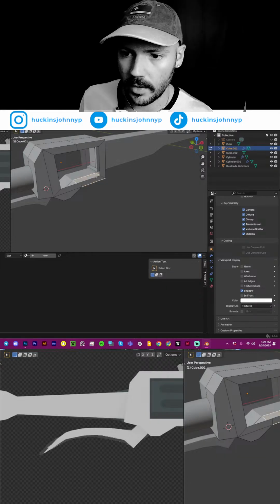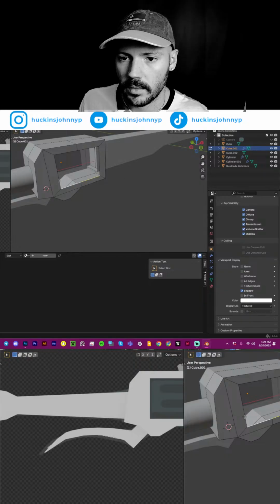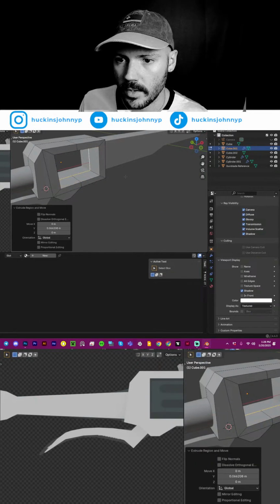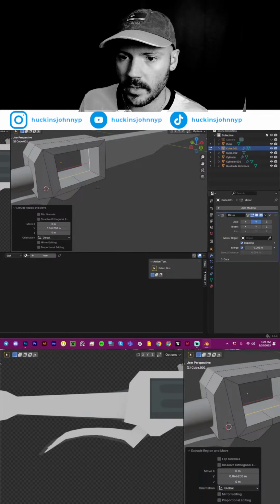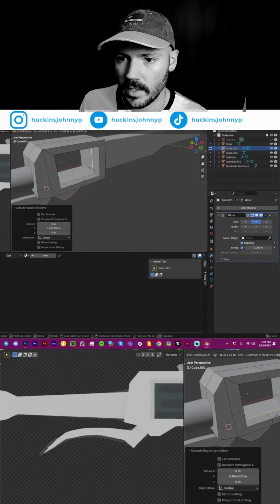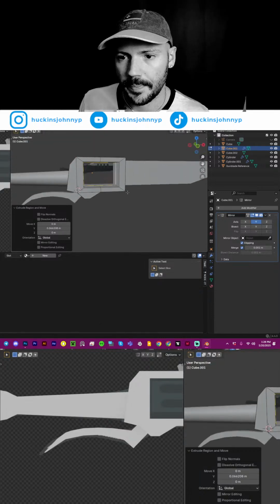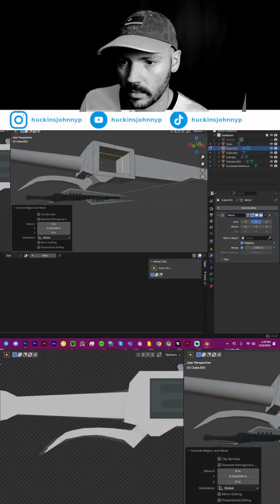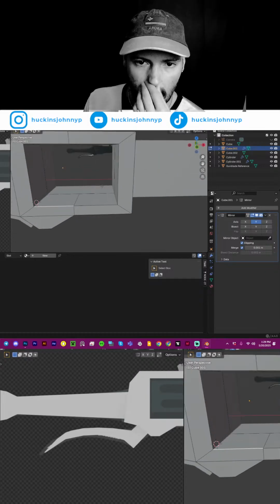And so if I go like this, and on 2, and I extrude on the y-axis, I can connect these two. And if I come here on my mirror, clipping is on. So now if I was to move these, they're connected, which is exactly what I want. I want those connected. Again, keeping quads wherever possible. Quad, quad, quad. Everything's looking fine. I like that a lot.